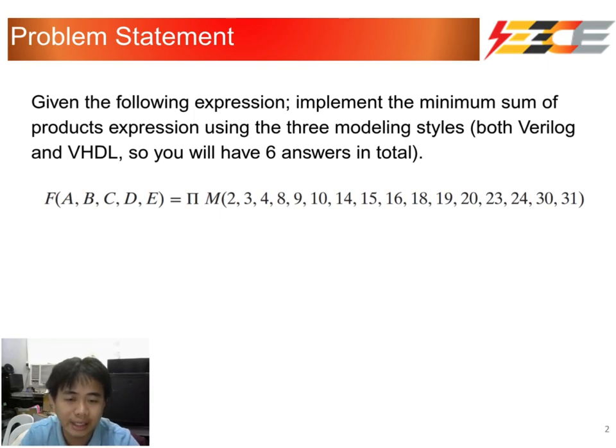So, here's the exact problem statement. The function was given as a product of max terms. My goal is to convert that to a minimized SOP, or sum of products, and implement the results in three modeling styles, both for Verilog and VHDL.